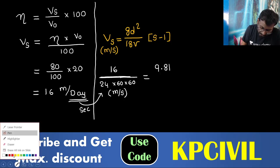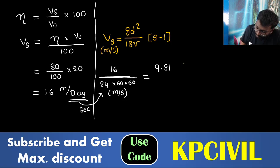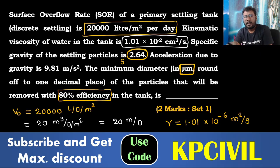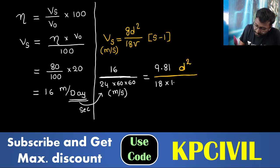Velocity in meter per second is equal to g, 9.81. D is the parameter we need to estimate. D square divided by 18 nu. This is the nu value, and we already converted units: 1.01 into 10 power minus 6. So 18 into 1.01 into 10 power minus 6.